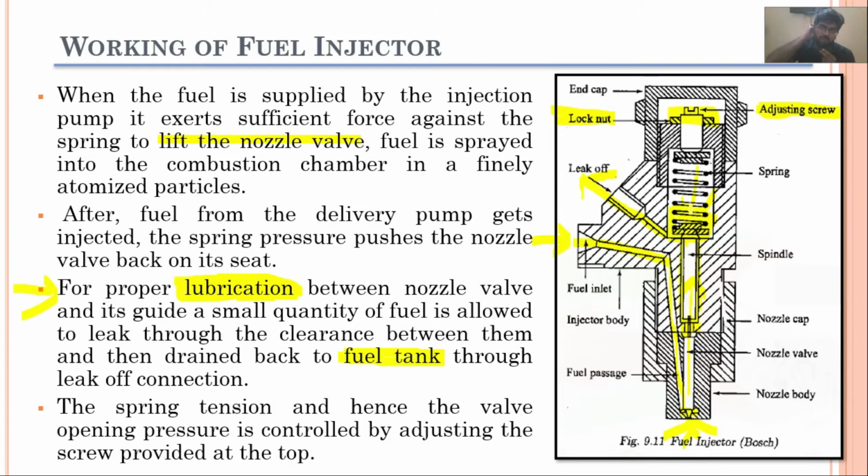Similarly, if we have a pump which is operating at some higher pressure than the design pressure of this fuel injector, we can tighten this screw, so the amount of force which the spring will exert will increase, and this nozzle valve will open at the higher pressure. In that case we can utilize a pump which operates at a bit higher pressure as well.